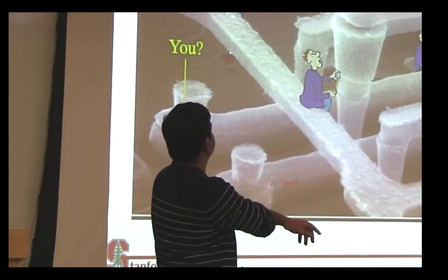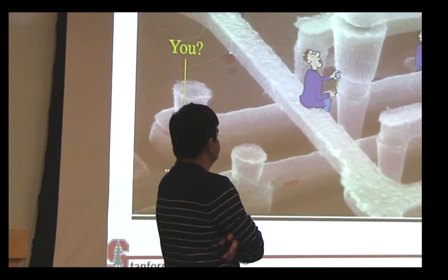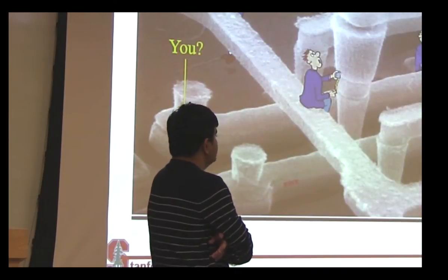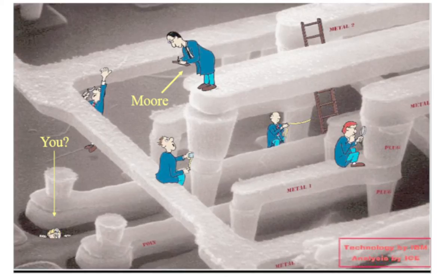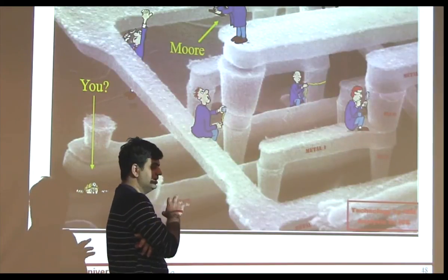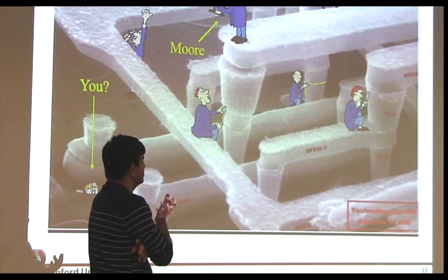So the point here is you can scale down your transistors, but as long as your interconnects are not scaling properly, and we'll discuss later that essentially if you scale an interconnect, its delay does not scale. The RC delay of an interconnect with scaling remains constant.